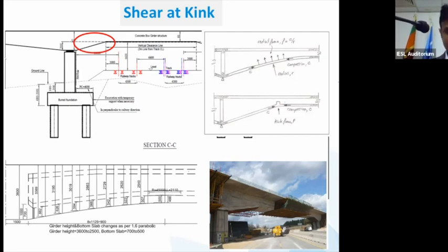In fact, I was so confident that we could go with this because in the UK I had a number of similar types of bridges which I referred to, and this is one of them. But there is stress concentration. So I would urge, if you are doing post-tension box girder bridges, maybe applicable for any, that if there's a sudden change, that is an area of concern always. Please be mindful of that area.